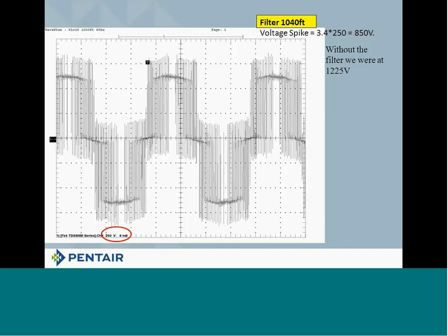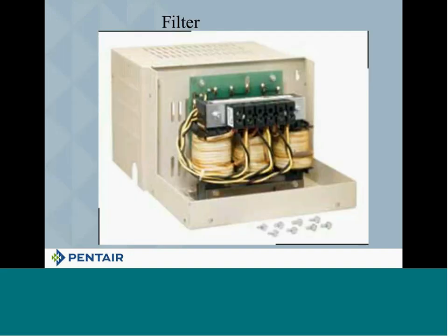So, when you look at your 1,040 feet, we're at 850 volts. Geez, look at that. We can even use a standard motor here as long as we put a filter on it. Now, what does that filter look like? Well, if you look at the filter, it looks like this.